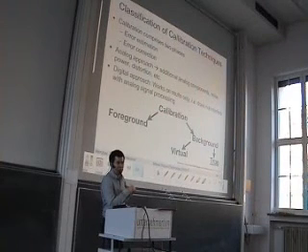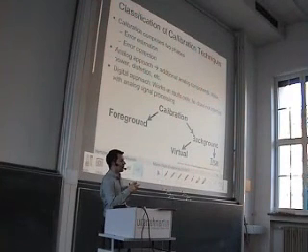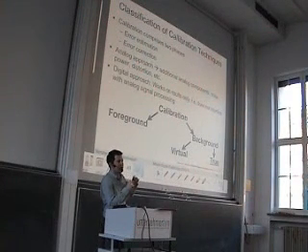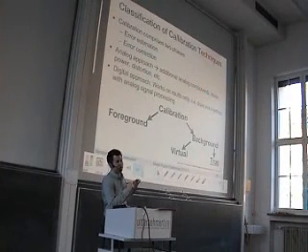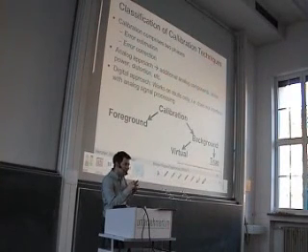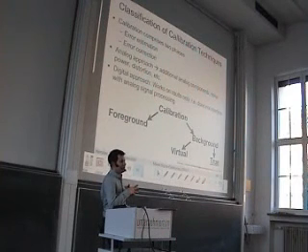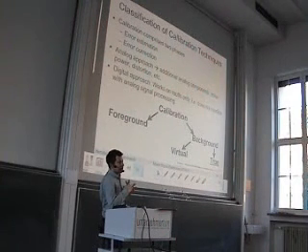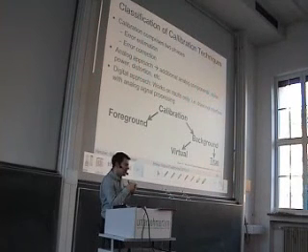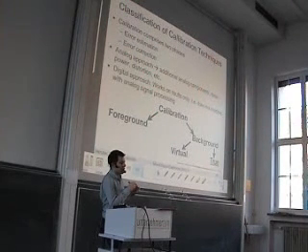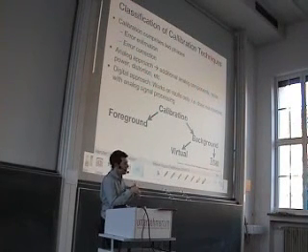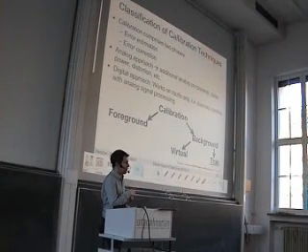The first techniques for calibration were analog approaches, where I measure my error and then adjust the gain by adding some capacitance or some resistance to a node, doing analog tuning. However, this approach is somewhat limited and causes some trouble, because by adding these calibration elements, you add additional analog circuit elements which cause parasitic capacitance, which may cause noise, which cause area, and so on.